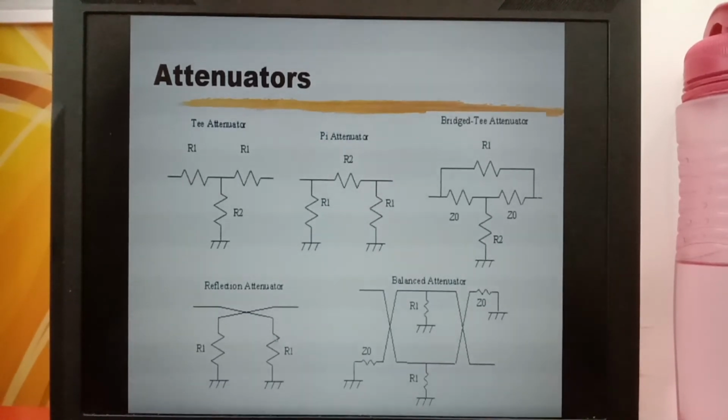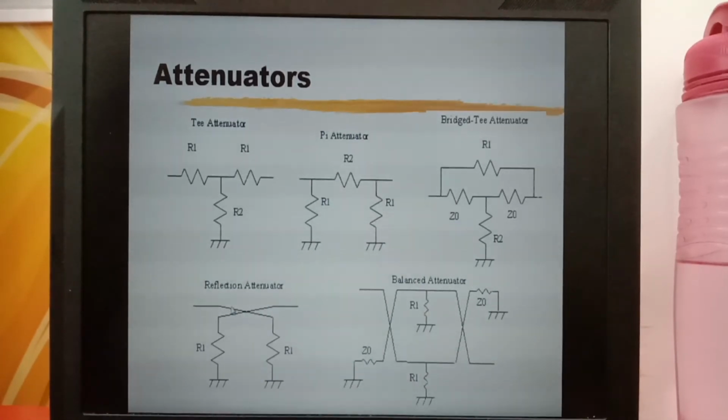That means we will get some reflection. The reflected signal is again split. Half of the power will go back to the input, and half of the power will be transmitted to port 4, which is again terminated by R1, and this will also give rise to some reflection.